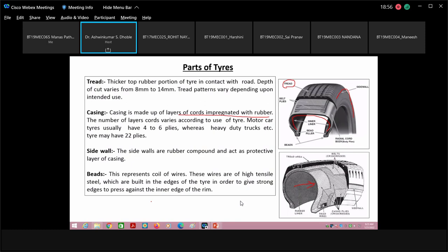See, the number there signifies the wheel radius, as rightly pointed out, which is given in inches, and there are some letters which are printed on that. We are going to see what is the meaning of those particular letters. The significance of that number is basically that it gives the metric designation of the tire, which is accepted worldwide, and it is decided by SAE. So we will see what each and every letter in that tire number means in the side wall.